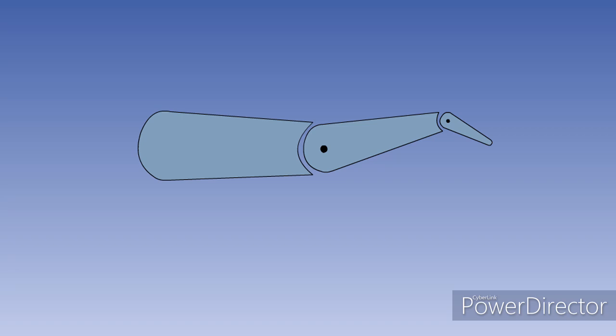You will recall from the aerodynamics lessons that the hinge moment is equal to the aerodynamic force, multiplied by its distance from the hinge line. In this example, the control surface hinge moment is distance A multiplied by force F2.